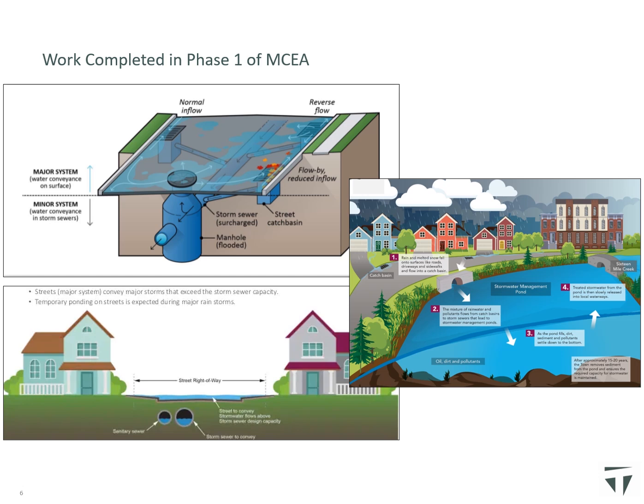The major drainage system consists of the roadway and overland flow routes, which convey storm runoff when the capacity of the minor system is exceeded, as well as the various watercourses and culvert crossings throughout the town. The major drainage systems are designed to prevent flooding during rare storms such as the 1 in 100 year return frequency design storm or the regional storm, typically once-in-a-lifetime storms.